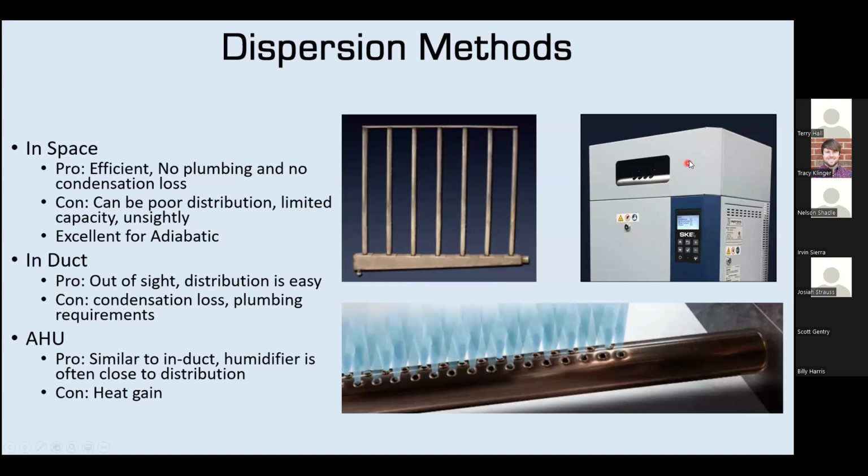It works really well for, let's say, a computer room or maybe a laboratory where it's fairly cold and you don't have enough airflow. You can't put the steam in the duct because there's not enough airflow, or it's too cold and you'll condense. This works well for that. But it's limited capacity.